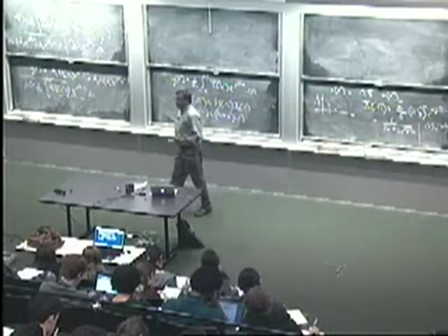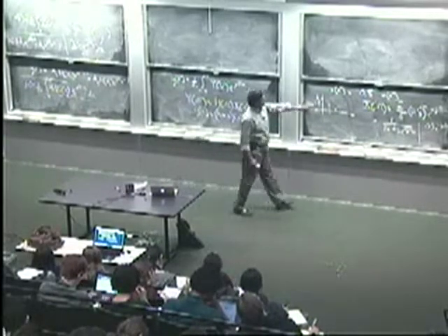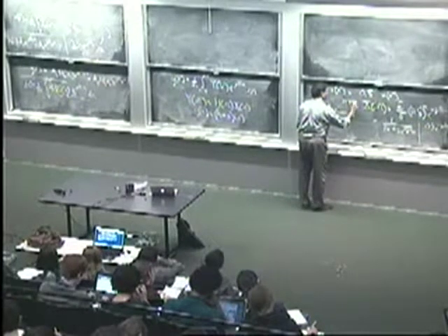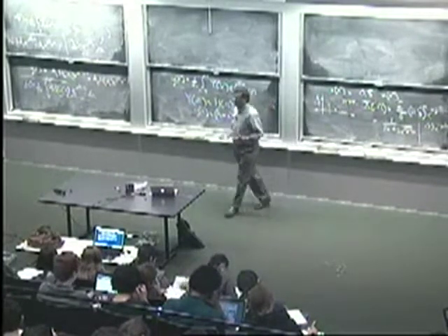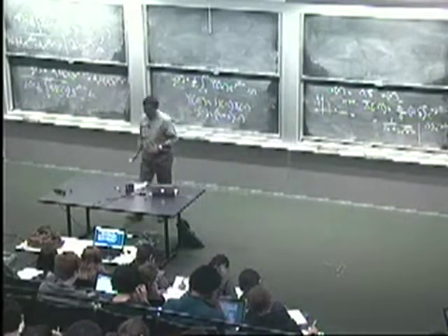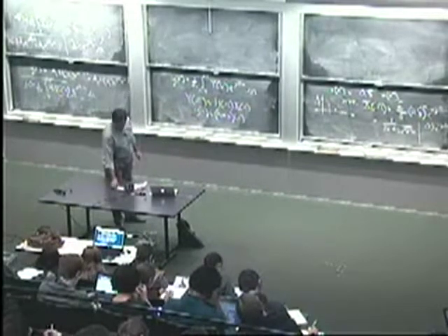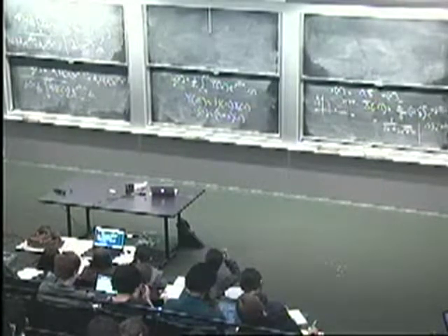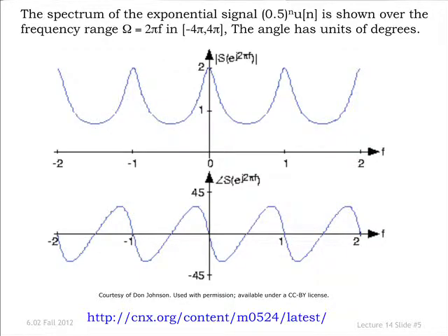So if you wanted to figure out the spectral content, you first compute the DTFT. And then the most helpful way to get a feel for the signal is to look at the magnitude of the DTFT. And that's what's actually plotted in this case. This is taken from somewhere that used slightly different notation, but we'll talk through it. What happened to the top of my slide here?